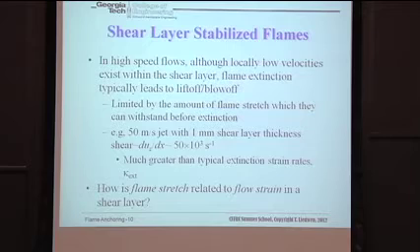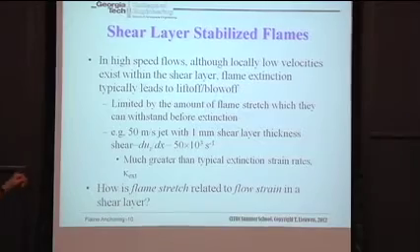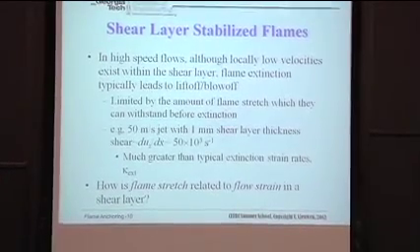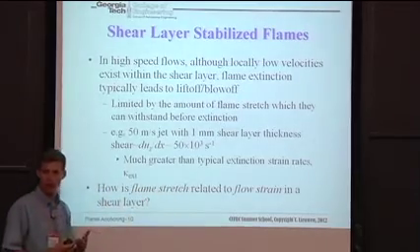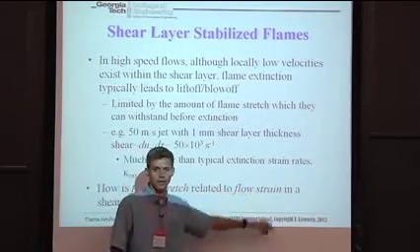Just for your context, but I want to emphasize this is fluid mechanics strain rate. If you think about your shear flow, your first graduate fluid mechanics class, we talk about fluid mechanics strain. That's what I'm calculating here. Now this number is much greater than typical extinction strain rates. Extinction strain rates for methane-air at standard temperature and pressure is a couple hundred inverse seconds. This is really high. But this raises the question: what is the relationship of flame stretch, which is this quantity that flames are sensitive to, to fluid mechanics strain in a boundary layer?